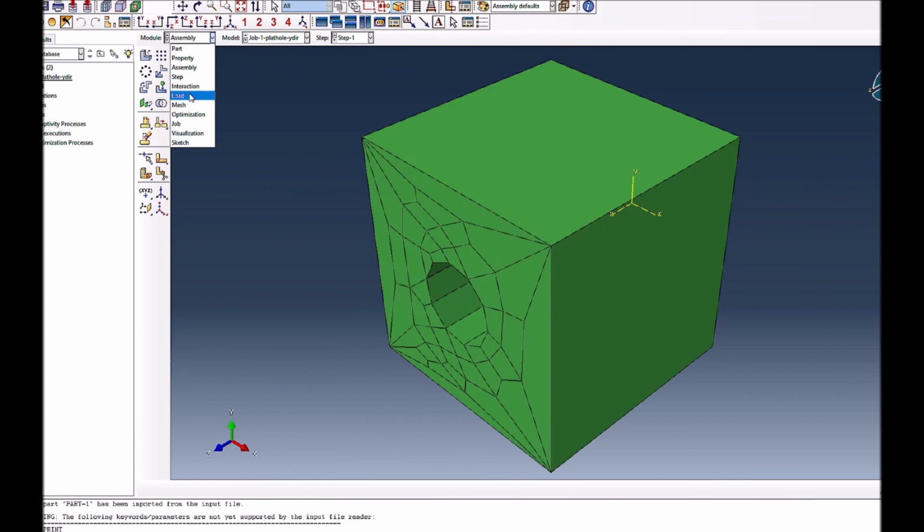So let's look at the boundary conditions. Firstly, the mesh is not optimized. I would not really recommend using this kind of mesh. You need a very fine mesh in these kinds of models. So you go to the loads and you can see there are some fixed boundary conditions, and then there's a boundary condition in Y direction.